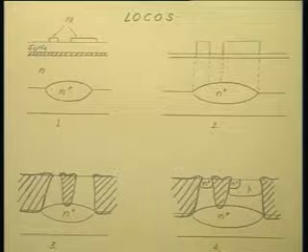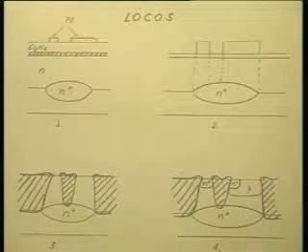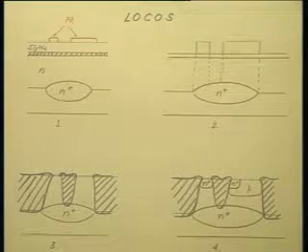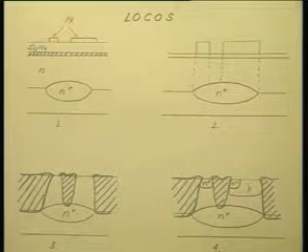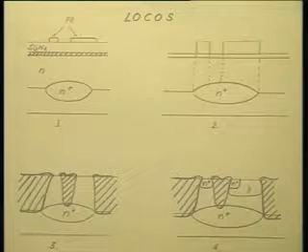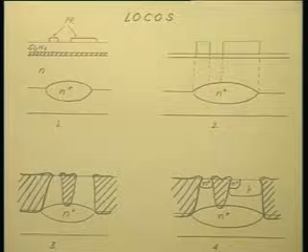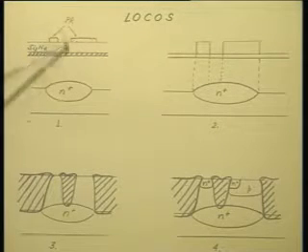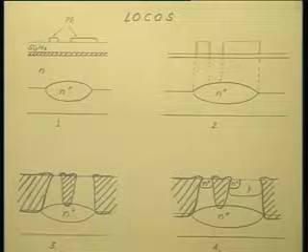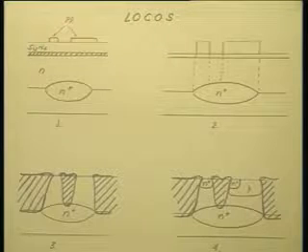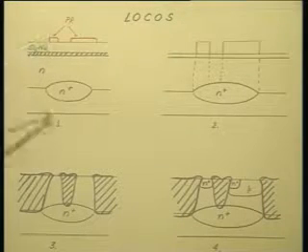Si3N4. This has to be chemical vapor deposited silicon nitride, stoichiometric silicon nitride. The plasma deposited ones do not work very well. So, most people use chemical vapor deposited silicon nitride. So, on top of this you have chemical vapor deposited silicon nitride and then you have a photoresist pattern on that. That is, some regions of the silicon nitride are protected by photoresist. So, this is your first figure.